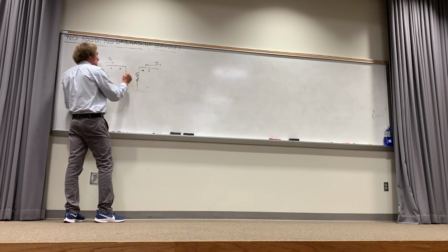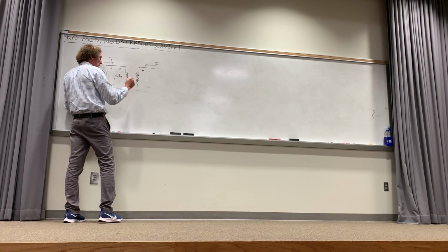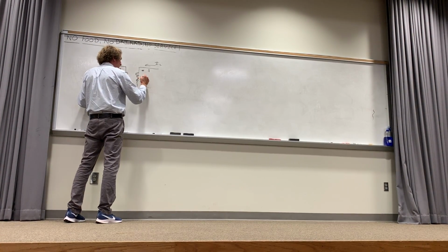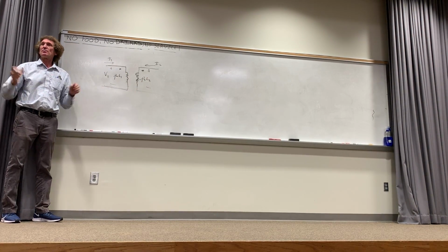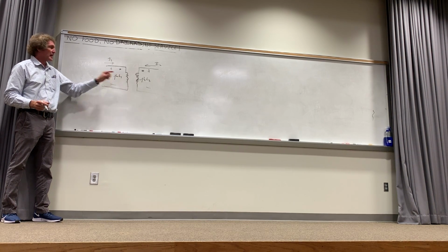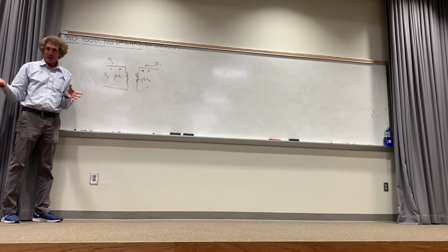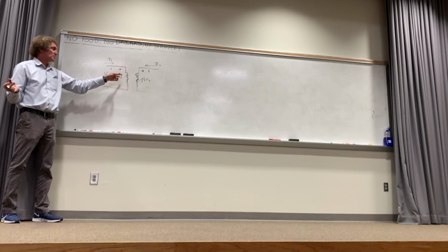Here we're going to have an impedance at this side that is going to be given as J omega L1. There'll be an impedance here that's J omega L2. Now I want you to just understand something. If that's all the problem showed, then the voltage V1 would just be I1 times J omega L1. Does that make sense to everybody? That is if it's a non-coupled circuit. If this is just an inductor right there, then V1 is simply J omega L1 times I1.